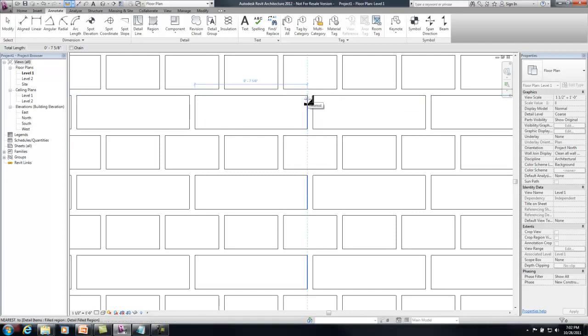So leaving it at that 1 inch import scale created bricks that are exactly the size that we need. There are also other third-party options that you can use to create custom patterns. One of the companies is called HatchKit. You can easily Google online and look for other third-party hatch pattern creation tools.